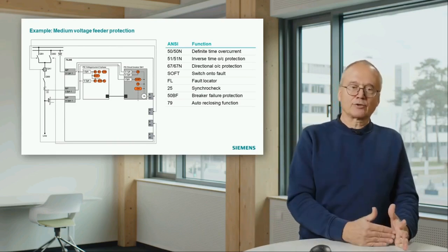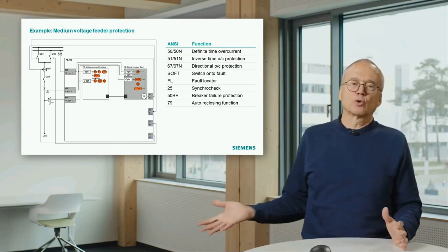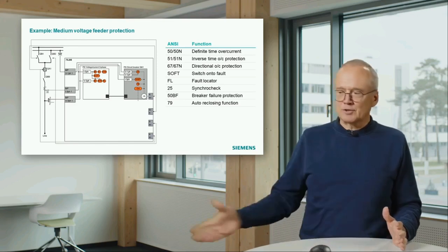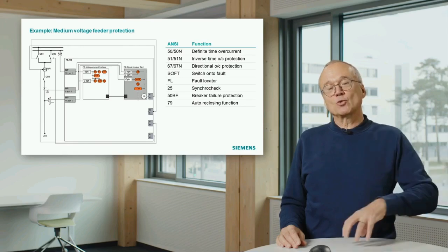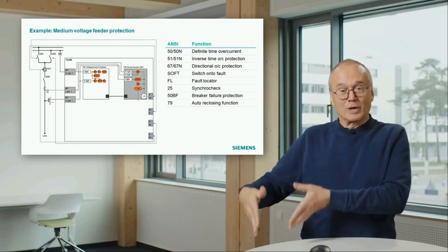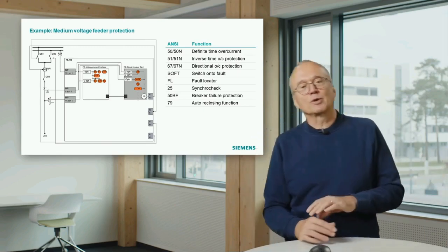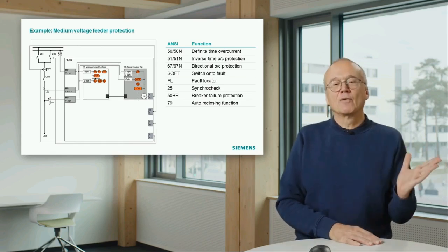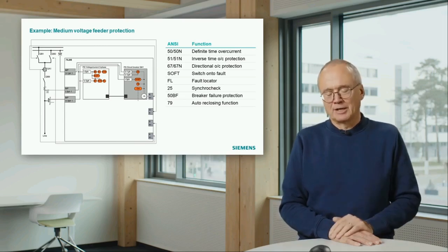you reconnect the feeder and somebody forgot to remove an earthing switch or whatever. That means you still have earthing in the feeder, you close the breaker, and that means you connect the part of the system where there is still earthing to the bus bar with nominal voltage. And that means in the moment where you close the breaker, you directly see a fault.